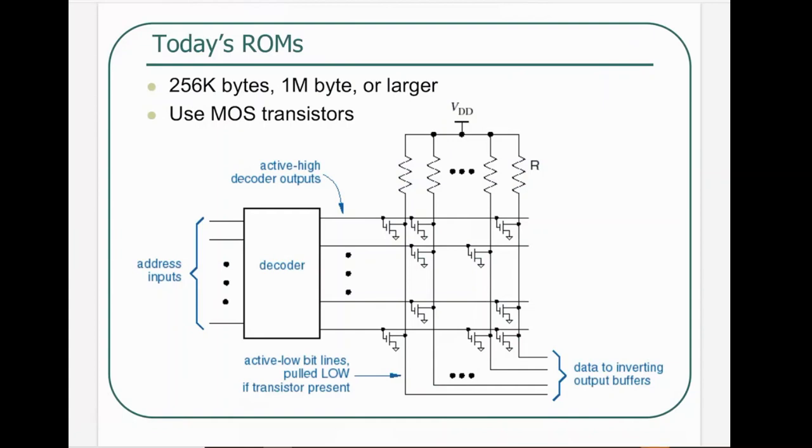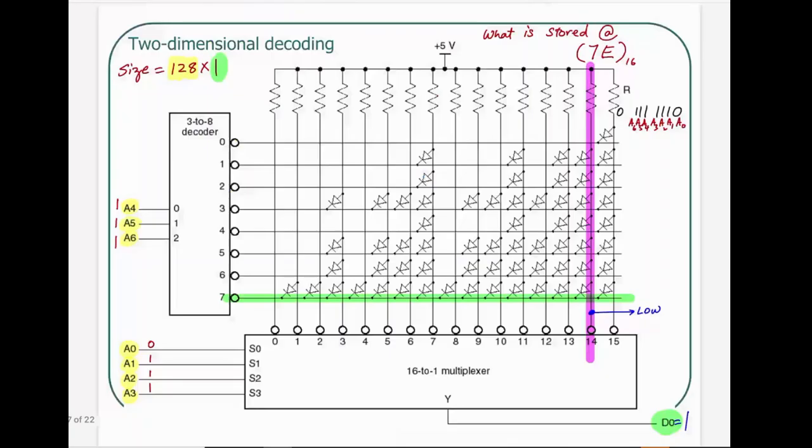So we started there, and then we moved on to a two-dimensional decoding example like this, where we were trying to read a particular cross section, like a particular 1 bit. Again, we are not changing any bit here. The bit is being assigned by the location of the diode, but you could give an address over here and then read whatever is stored at that location at D0. So we looked at that particular configuration. This was the last thing that we did in the last class.